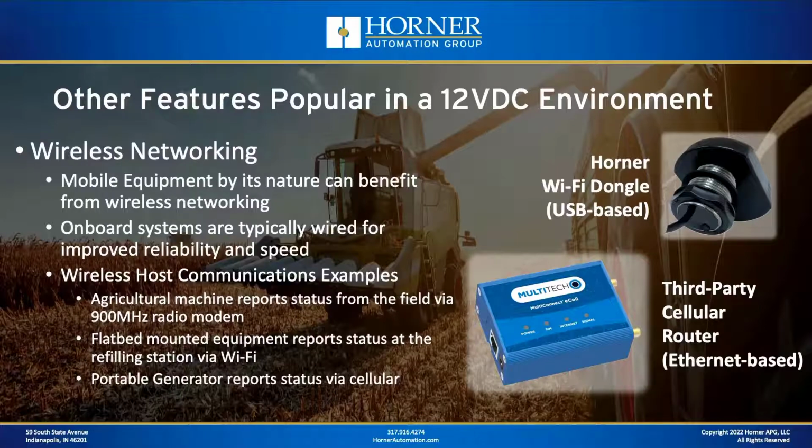So all of these types of scenarios make wireless communications with a piece of mobile equipment valuable. From a Horner perspective, we offer a really nice, inexpensive Wi-Fi dongle that plugs into any OCS that has a USB-A port, and it can add Wi-Fi to the OCS without using up the wired port that's already there. So if you have an XL4 you want to use with a wireless network, but you also need to use it with a wired network, no problem. You can add the Wi-Fi dongle and you get the benefit of both wireless networks talking to that XL4.